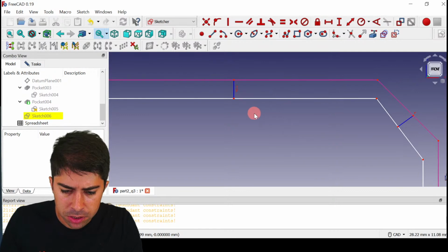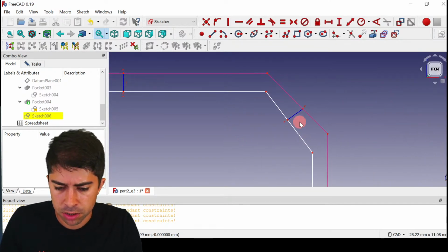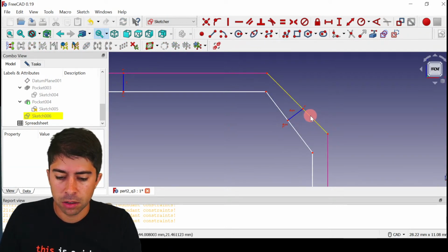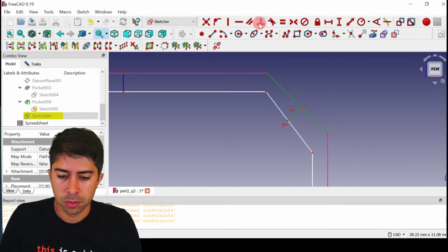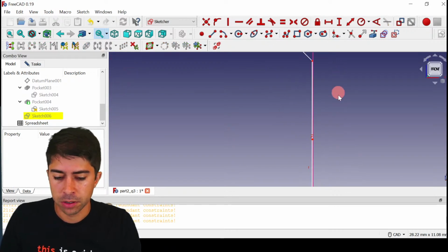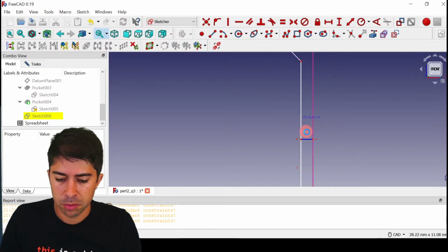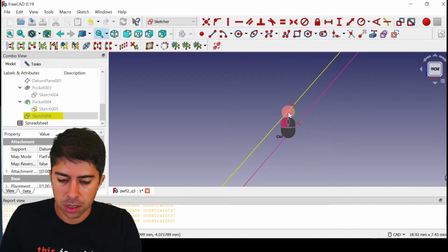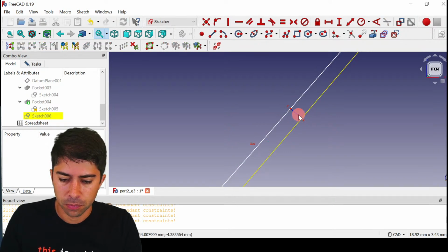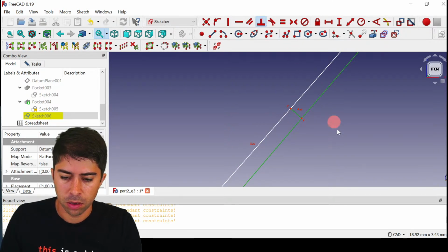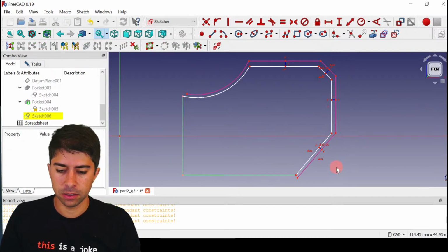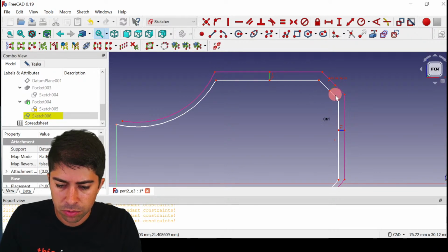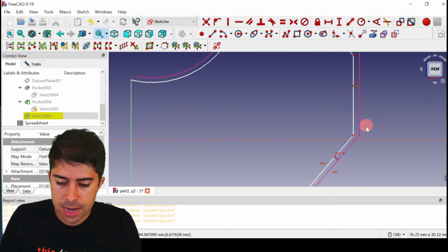Or it will just update as well. So that one, is it straight? Yeah, that's straight. So I just need to create a constraint perpendicular to that, and that one needs to be perpendicular as well. All right, so it updates that. And let's just move that line a bit. And then this one also just needs to be given that constraint. Okay, so we got that. Okay, so everything's fine. Now I just need to tell them that all four of these are equal in length.